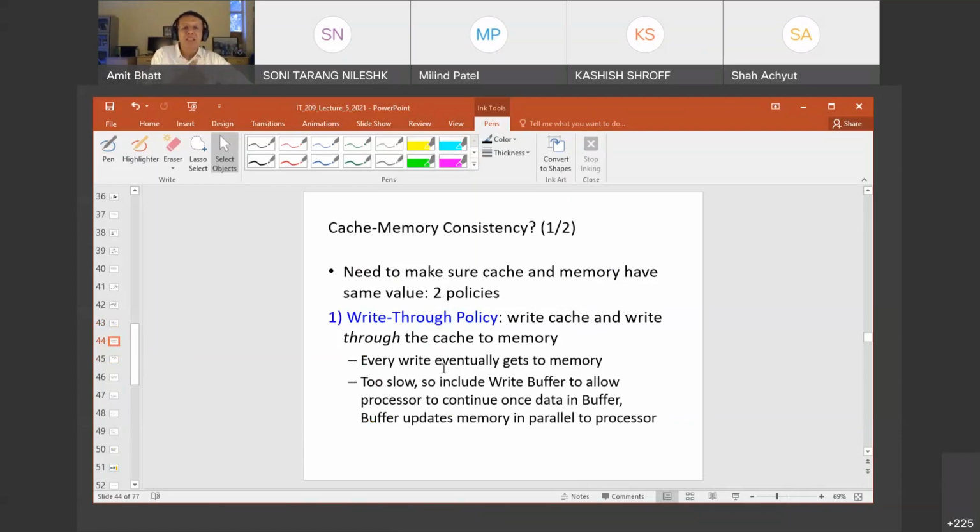While it is changing from L1 to L2 and L2 to L3, suppose there is a similar demand for some cache memory which has to be brought from L2, then L2 would say, okay, at the moment I'm busy in updating one of my blocks. Once that block is updated, because signal lines are common. So whether it is getting data from this side to this side or sending data the other way, it has to use the same road. When I say road, I mean the same signal lines. So in that way, it would slow things down.